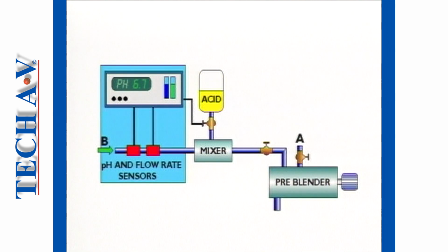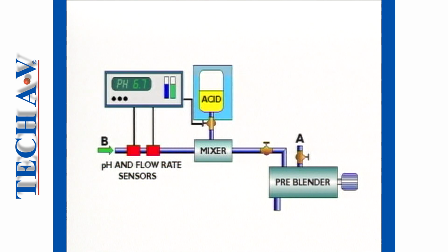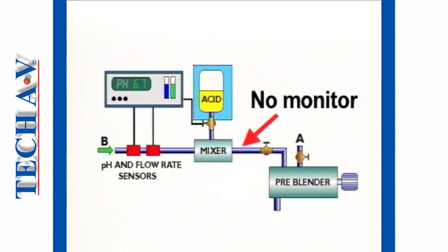The feed-forward controller had worked well based on the flow rate and pH of the component B. But on the 3rd day, the concentration of the acid additive varied considerably. And since there was no control system to monitor the pH after the feed-forward system had adjusted it, the pH remained high. You may recall that we mentioned this limitation when discussing the feed-forward controller.